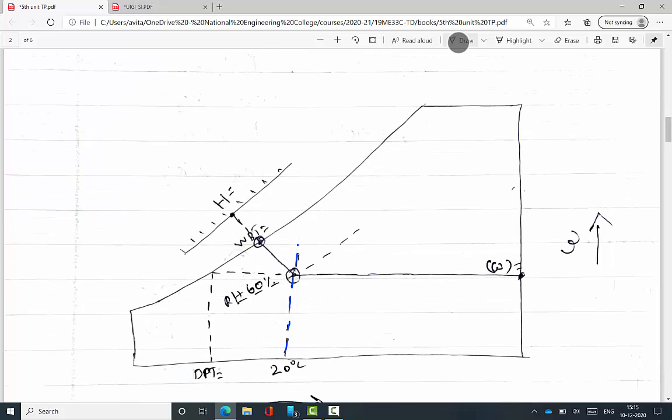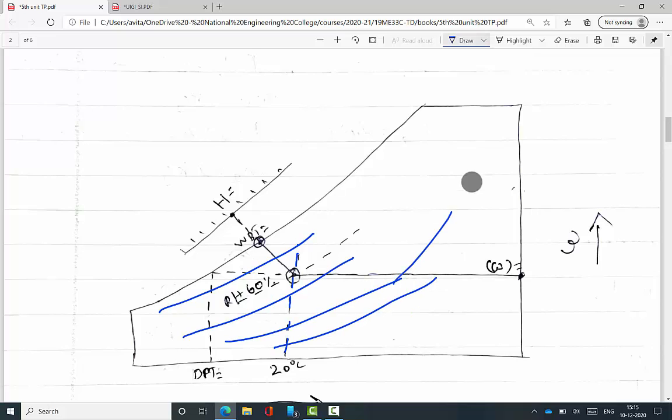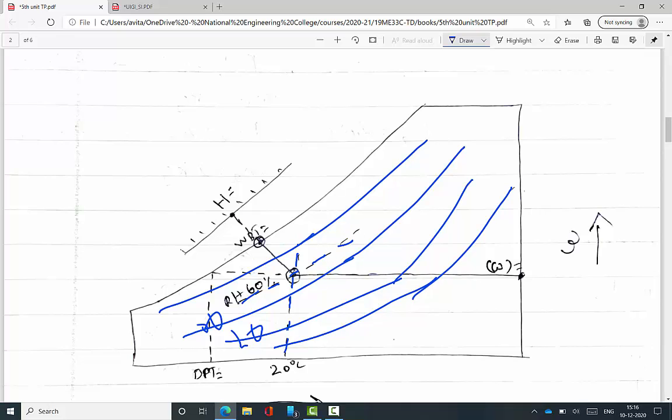Likewise the relative humidity lines are there, 40%, 50%, therefore at 60% I draw an imaginary line. That vertical line and the curve intersect at one point. That point is our location.